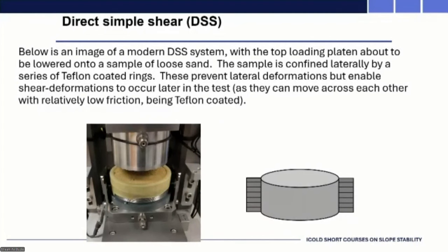But increasingly we're looking at as well is, as you're consolidating it, you're incrementing that shear stress, because the only way you can load this test is vertically and by applying a shear stress at the interface. So you actually impose that shear stress. So when you have a test with so-called bias, it means you've consolidated under an imposed shear stress, which is probably what's happening, certainly beneath the slope. It's not the case under horizontal ground. There the K0 is probably quite adequate.